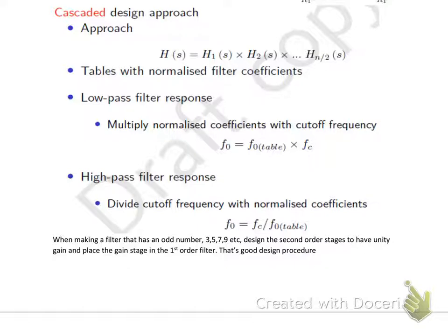You can either design the whole thing yourself from beginning to end and cascade the amplifiers together, but there are certain things that you have to keep in mind, like having a dominant pole, making sure that all the poles are at least 1 magnitude away from each other, and the last thing would be your stabilization, because you are designing an amplifier that has more than 2 poles, so there is a chance that your amplifier may be unstable, right?